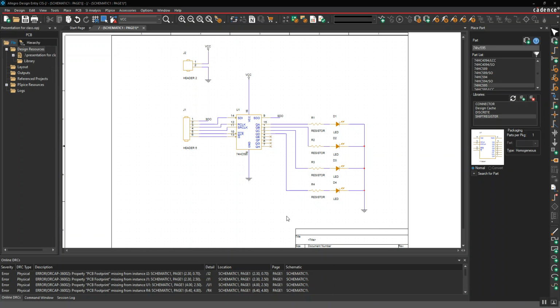Here we're going to talk about applying footprints to the different components in your schematic. So the schematic doesn't have to match up to how it's actually going to look on the board. If you notice here, this is not how the pins are going to be laid out when you're looking at the actual package. You'll never have a situation where you have more pins on one side than the other, and it's kind of odd that they're going to come out the top and bottom like that.